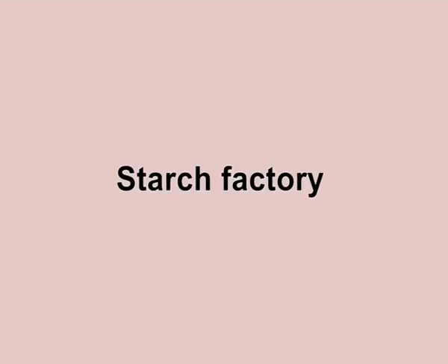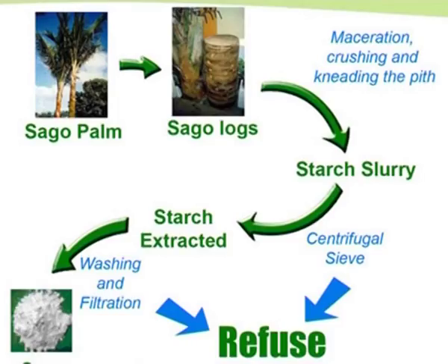So, treatment methods employed in different industries is the last topic of today's session. One important industry is the starch factory, where the wastewater has high organic load and usually consists of easily degradable matter. The undissolved organic contents are mainly carbohydrates and proteins. The fat content is normally 10%. Usually, this kind of wastewater does not contain any toxic substances.